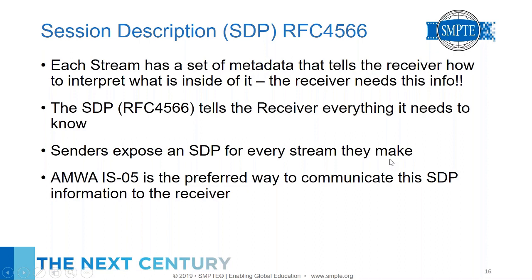So one of the things that this ISO 5 relies on is something called session description. So you'll see when you read the 2110 standards that probably a third to a half of the characters in each document are really about session description and how a 2110 sender describes itself with SDP. And so all of this data about picture size and frame rate and colorimetry and sampling structure is carried in this thing called an SDP.